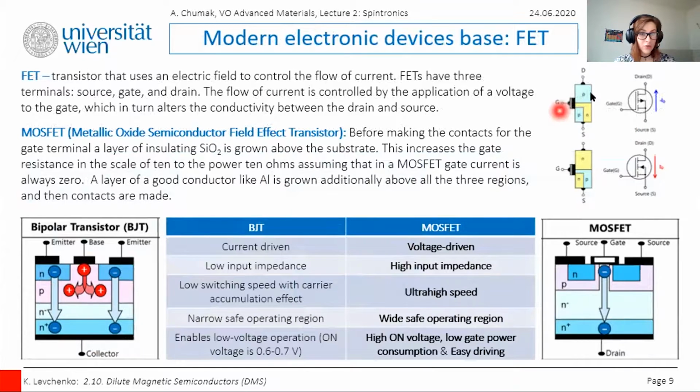So gate, drain, and source, and the N-type and the P-type field effect transistors are presented here. The semiconductor channel where the current flows could be either P-type or N-type, and this gives rise to the 2 categories of field effect transistors, namely the P-channel and N-channel. Further, we can divide field effect transistors into categories depending on whether the increasing voltage on the gate is depleting or enhancing the number of charge carriers available in the channel, thus creating either the enhancement mode FET or the depletion mode FET.